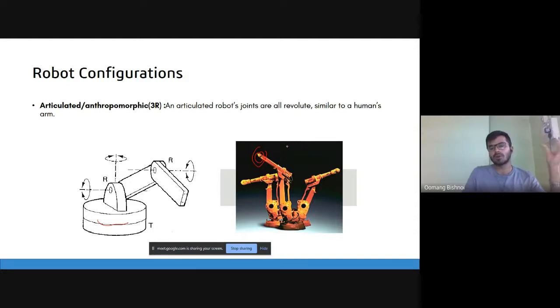So the default configuration of such robots is 210 kg payload, which comes from different companies like Yaskawa, KUKA, and Fanuc and everything. For these kinds of robots, we can integrate some kind of hydraulic system, and below that we can use the pneumatic system. As someone asked this question, this will answer your question as to the different applications, like this spot welding gun, which weighs like 200, 190 or 180 kg. We can integrate these kinds of systems. Okay.